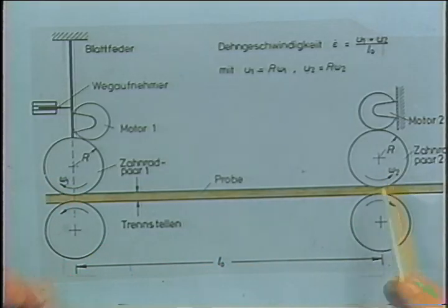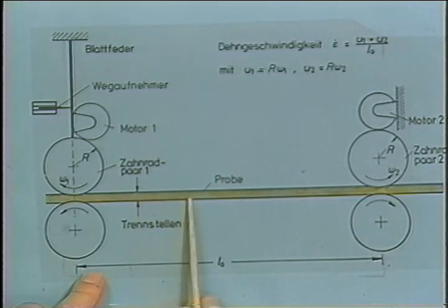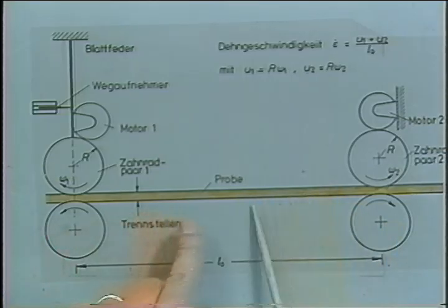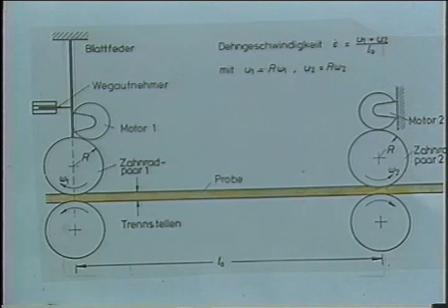And at the end of the experiment, Meissner cut the sample here at about 8 places and collected the samples after this cutting, and that told him whether the sample was uniformly stretched. He doesn't want to have any necking throughout. And whenever the weight distribution between those different samples is uniform enough, then he accepts the data. Otherwise, he would have to redo the experiment.